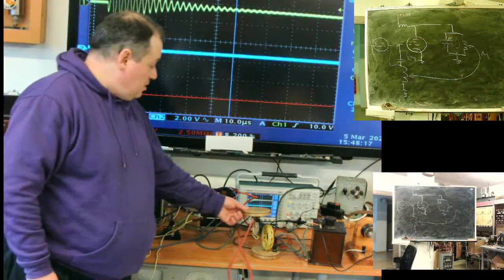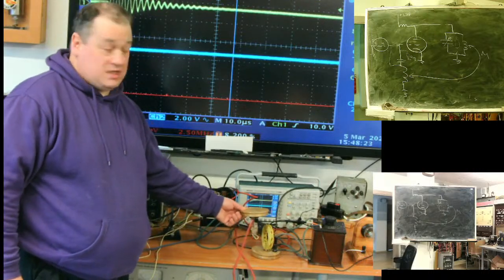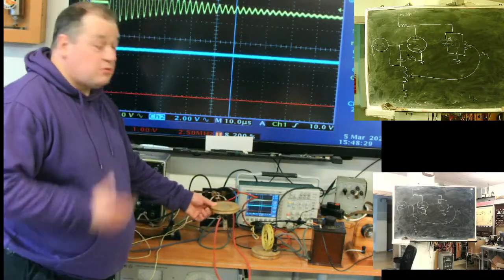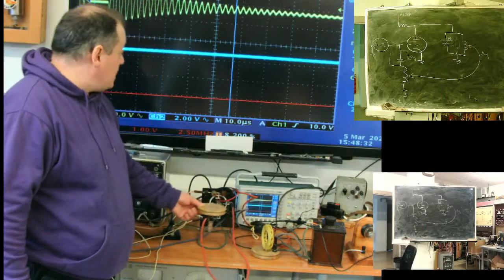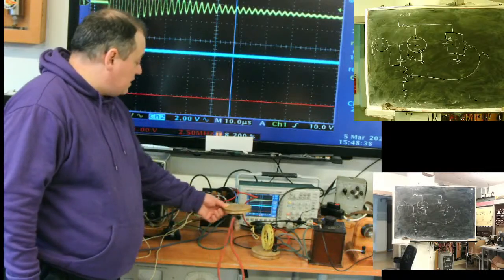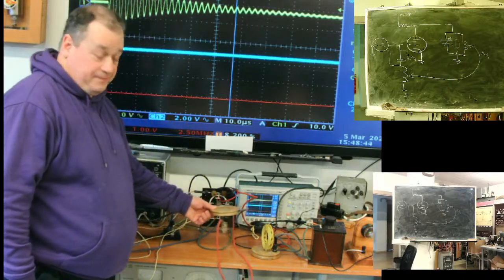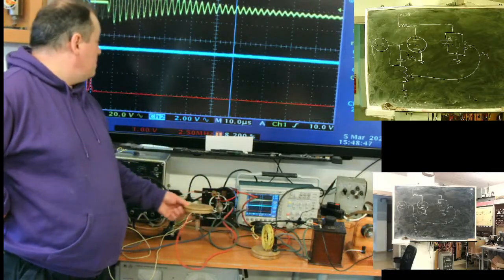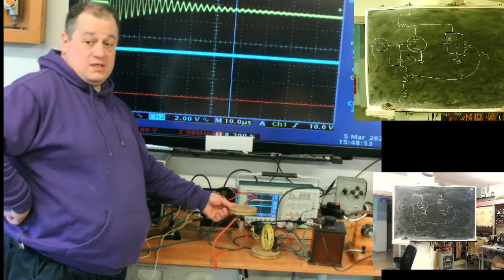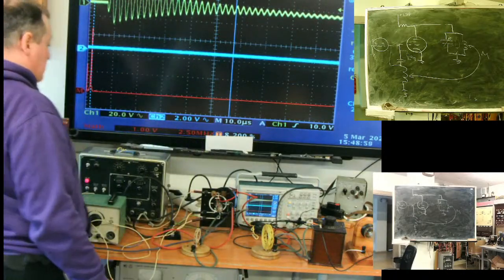Negative feedback makes the system more stable, as predicted. It's like choking it. Negative feedback increases linearity, and the key moment: negative feedback increases stability. This system is not willing to oscillate. Oscillates, nearly not oscillates. So negative feedback increases stability.